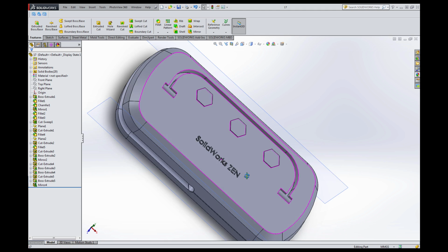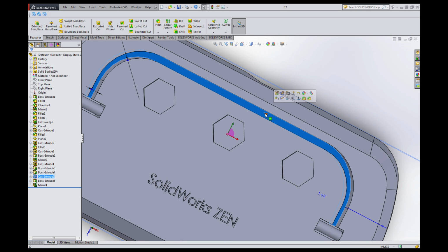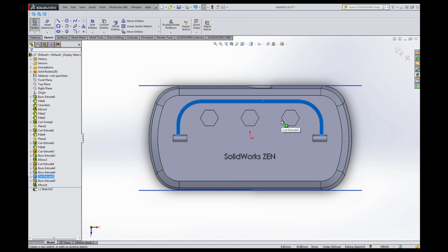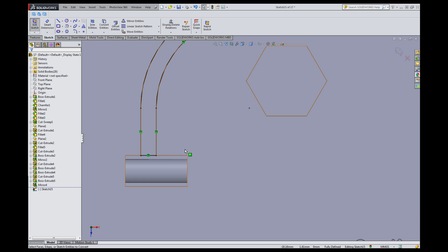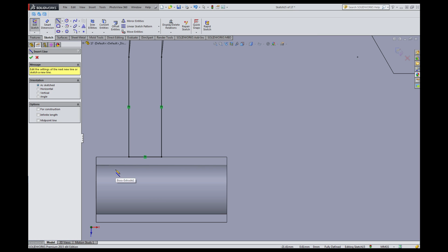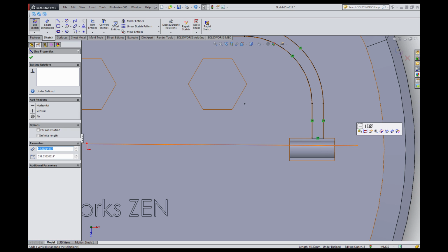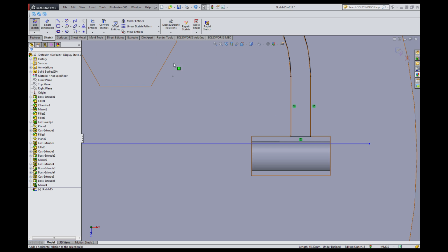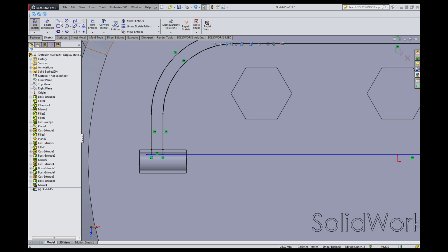Adjust the view, okay, and click on this surface, and select sketch, Control 8, and now I'm going to use this convert entities option, but I want that this line and this line not end here, but somewhere here, so I'm going to drag one line here, like this, and select this line and make it horizontal. Okay, and now go to extend entities and click here, here, here, here.